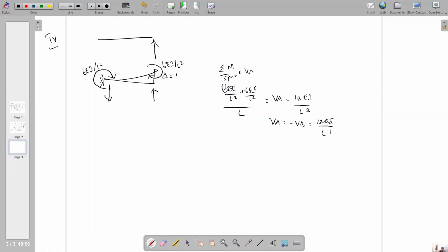Here the directions are reversed, so no need to put a negative value. We just put the magnitude of the reactions, that is 12EI by L cube. Now you mark the representation, which is K, due to the fourth coordinate effect. So K14, K24, K34 and K44.